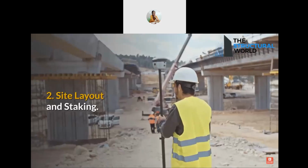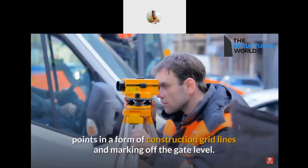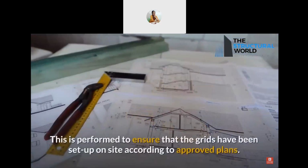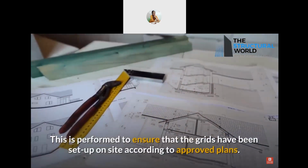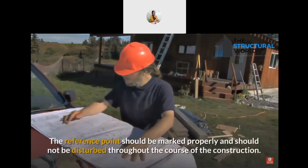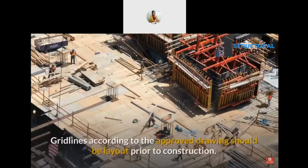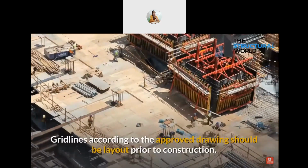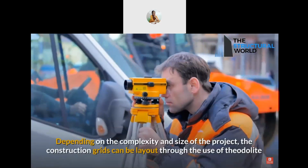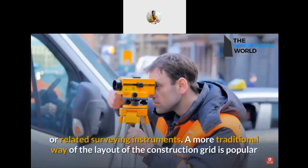2. Site layout and staking. This activity involves the setting of the reference points in the form of construction grid lines and marking off the gate level. This is performed to ensure that the grids have been set up on site according to approved plans. The reference point should be marked properly and should not be disturbed throughout the course of the construction. Grid lines according to the approved drawing should be laid out prior to construction. Depending on the complexity and size of the project, the construction grids can be laid out through the use of theodolite or related surveying instruments.